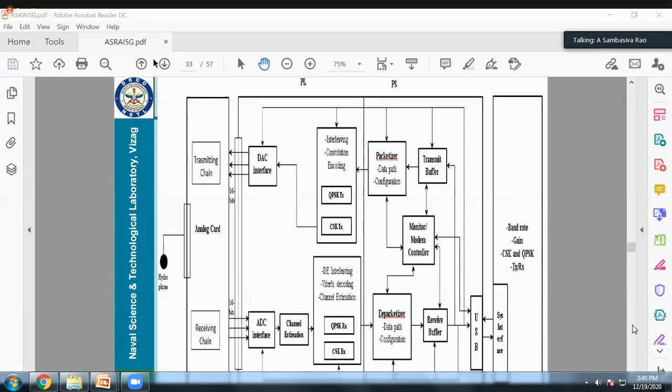They are not, because nobody is revealing their principle. They are telling us spread spectrum OFDM is going there. So in the initial experimental stage, I chose small, easy modules to implement, because if I go to complexity, I will be disturbed. Practically I cannot do that. So slowly, first I developed the FSK modem, and then other modems. Now I am working on the QPSK modem, and OFDM, MIMO OFDM also.